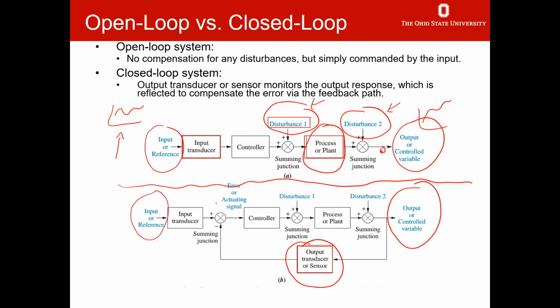Now the output we compare with the desired input in a summing junction, which gives our error. That error goes to our controller, which is what we'll concentrate on in the remaining weeks. Hopefully, if you've designed this properly, this will be stable, and it will, of course, make sure that there is zero steady state error with good transient response properties. Now, the root locus approach will make sure that we have good transient response, and frequency response methods are more for steady state.